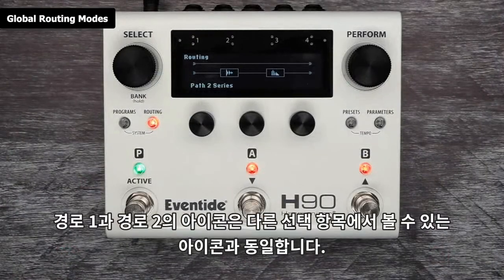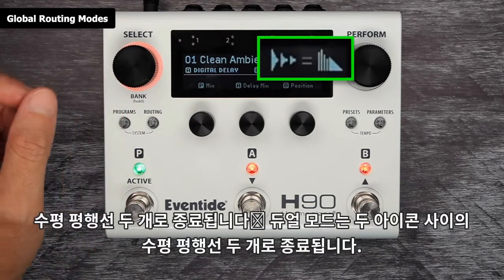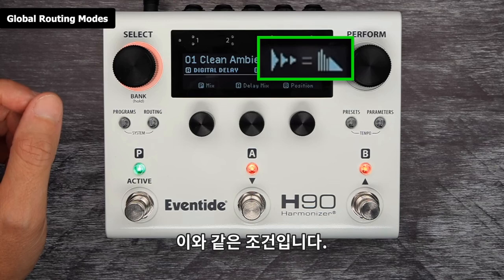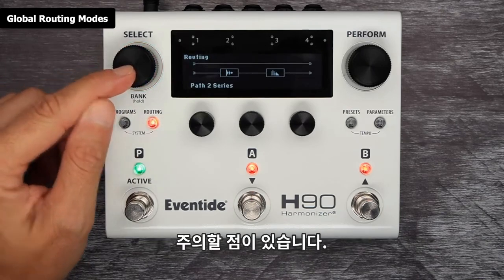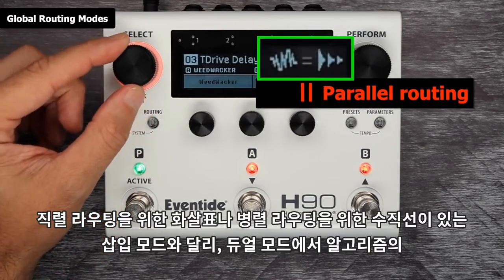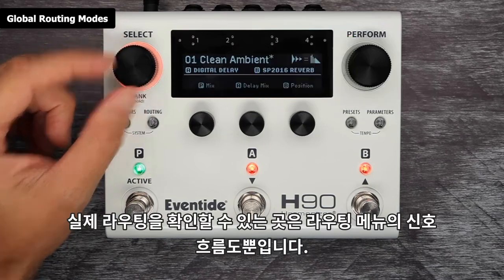Just like in insert mode, these are the same icons found on the top right of the select mode screen, where we can see the names of the algorithms. The difference is that dual mode is denoted by two horizontal parallel lines between icons. An easy way to remember it is, these parallel lines look like what we see in the routing menu. Something to note. Unlike insert mode, where we have an arrow for series or vertical lines for parallel routing, the only place where we can check the actual routing of algorithms in dual mode is in the signal flow diagram of the routing menu.